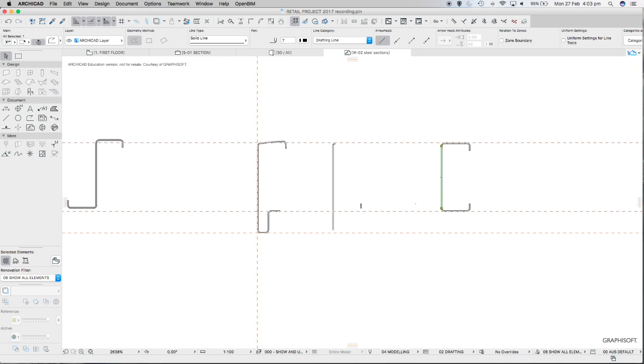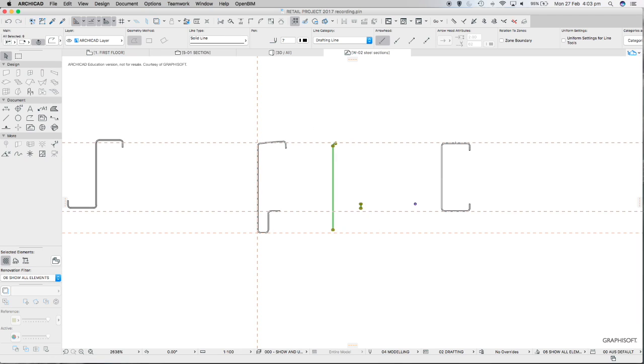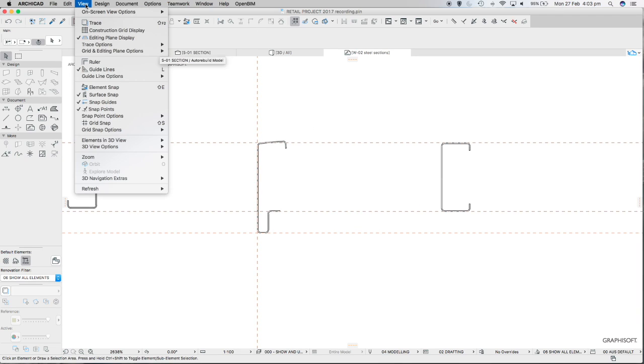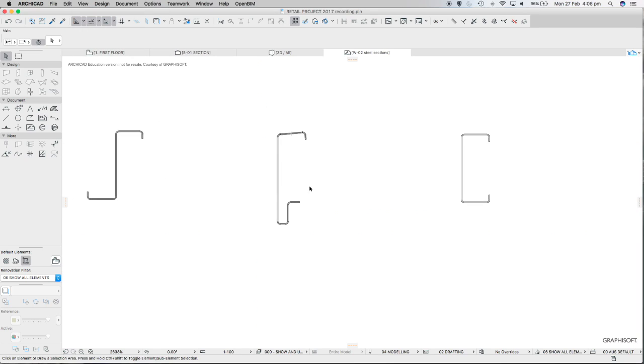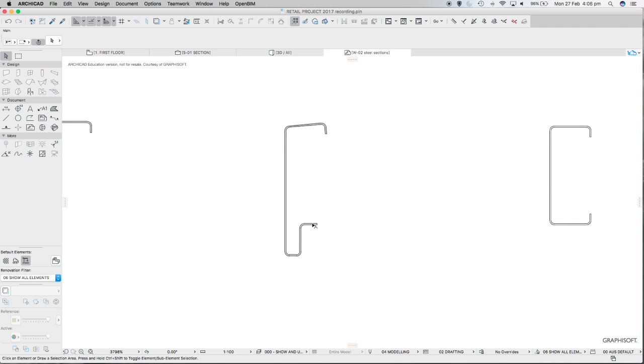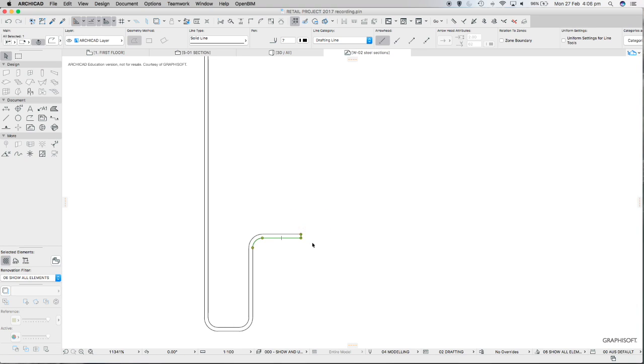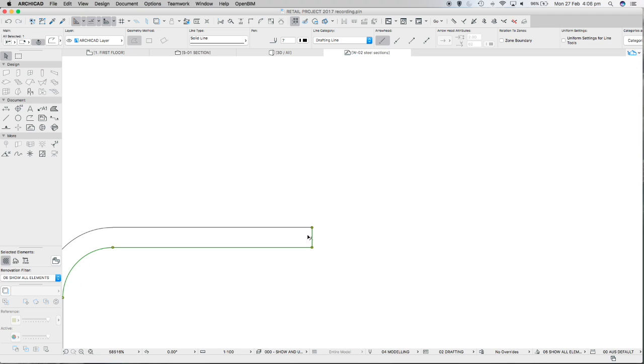I'm just going to leave this one in its entirety at the moment, but I'll clean up anything else that's lying around here, and we'll go to View, Guideline Options, Remove All Guidelines. Now, I'm going to back up on that a little bit because I've just seen a problem. We're going to need to rotate this bottom section here also by the 5 degrees like we did up the top. So select the fill and we'll delete that, and I can select that. Now it'll all rotate and then I'll be able to trim that up a little bit.